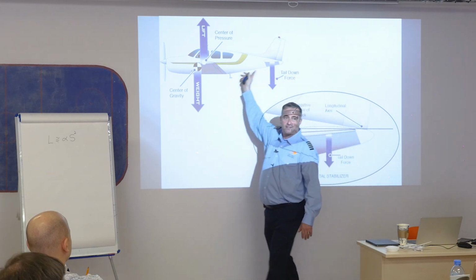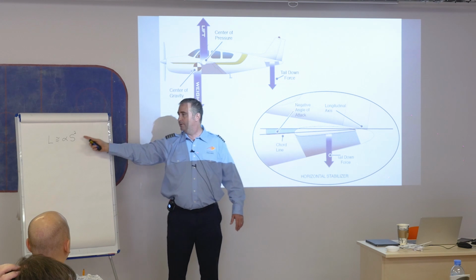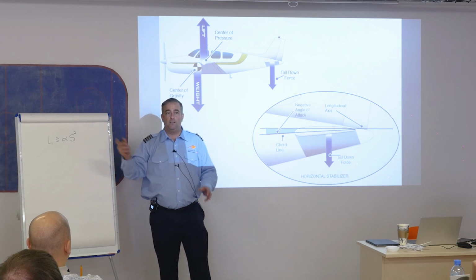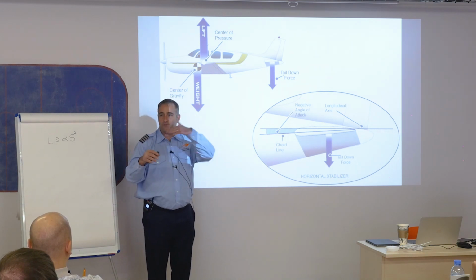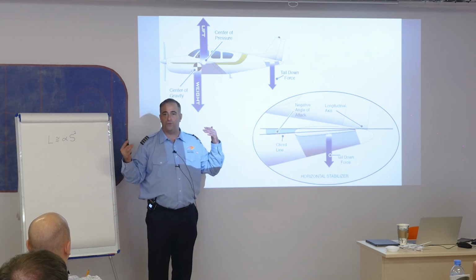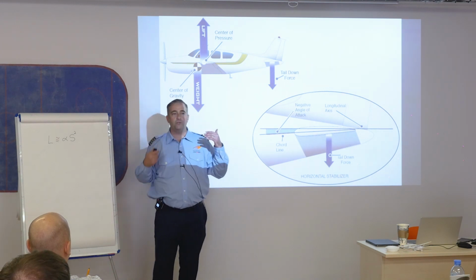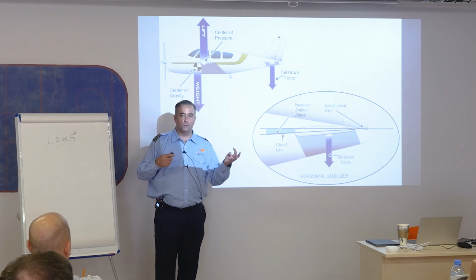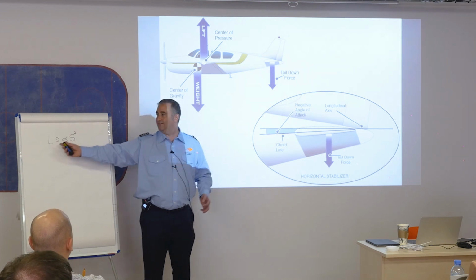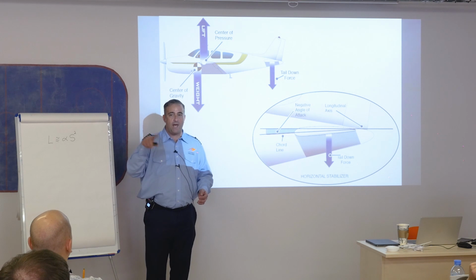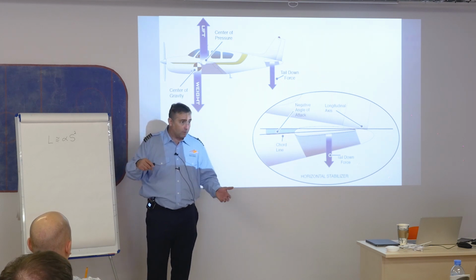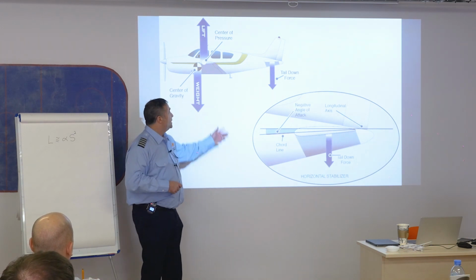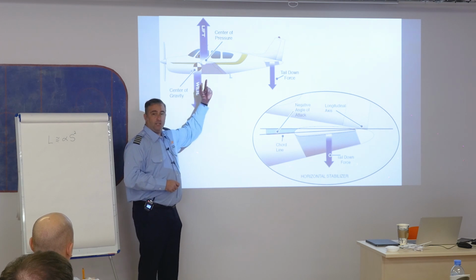All right, if I produce less relative wind, what's happening with my lift? A lot. So let's say I had 120 knots airspeed. So I got 120 knots worth of wind blowing over this thing. And then I reduce it, all of a sudden I only have 60. Well, I have half as much speed. How much less lift do I have now? 1/2 squared is 1/4. That's a big change. I got a whole lot less lift now. All right? So lift is decreased.